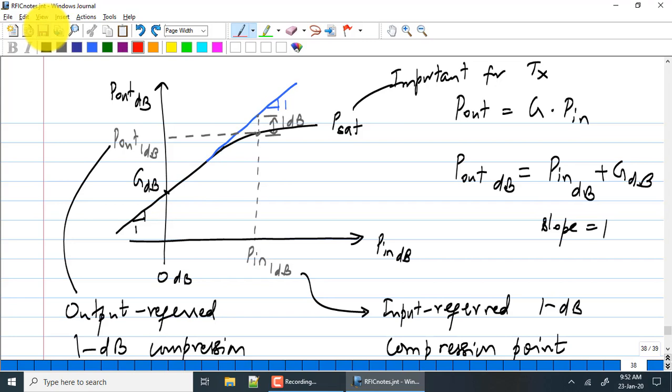You understand? I take two circuits. One of them, the Taylor series term is much worse, but the output swing limit is the same. The SNDR curves will be very different for the two. You need a much more sensitive metric. Number two, this metric also needs to take care of the frequency dependent nature of the circuit. If you define something where the term is going to go to the output and get clipped, etc., that's not going to work for us. So in next week's class, we will look at what this metric is and how we are going to define it.